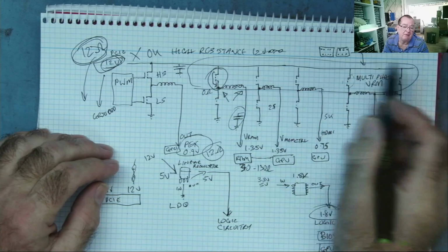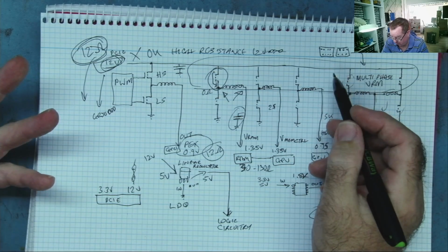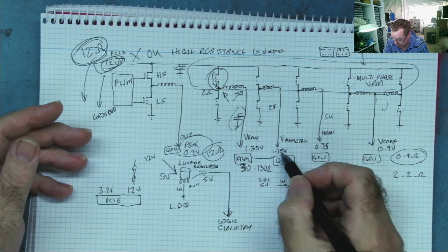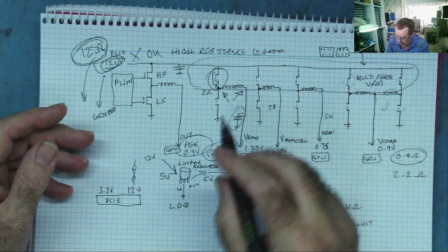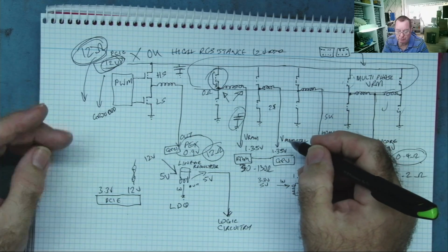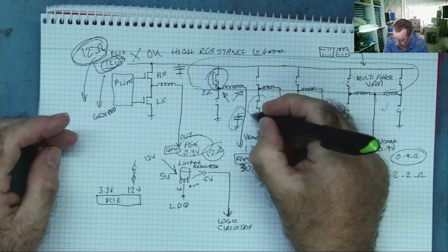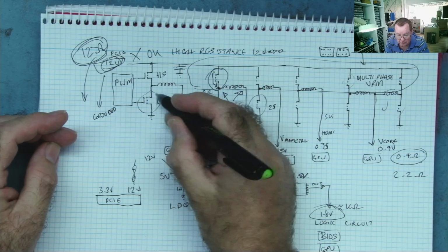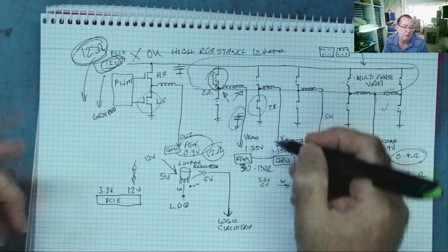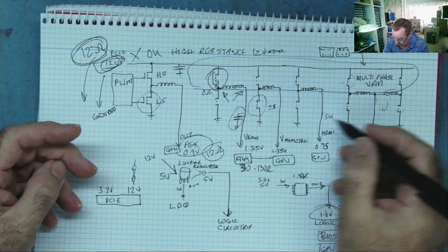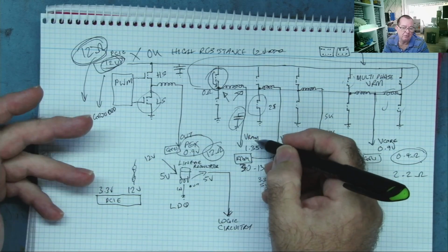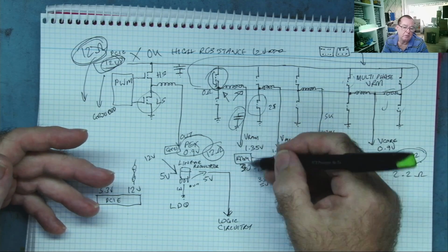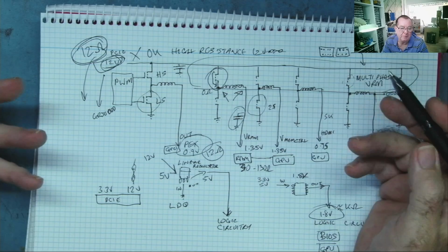If these are reading very high resistance, kilo ohms, mega ohms, this sort of thing, and you have a short on one of these, one of two things is wrong really. You've either got a short in the low side MOSFET, the one that's connecting to ground, on whichever rail, or you've got shorted capacitors on whatever the rail is powering, or you've got a shorted device, like for example short circuit RAM, on whatever that rail is powering.